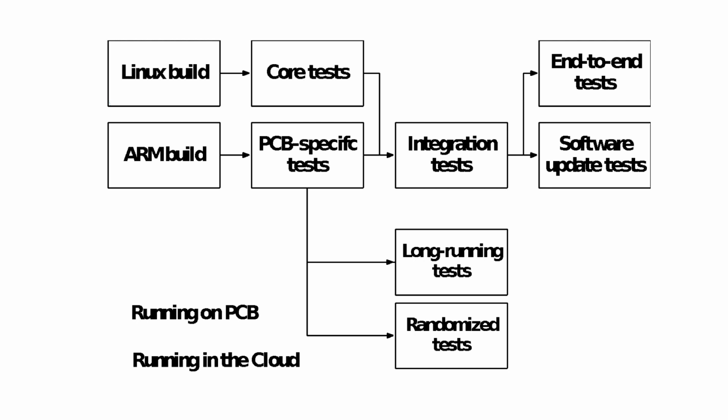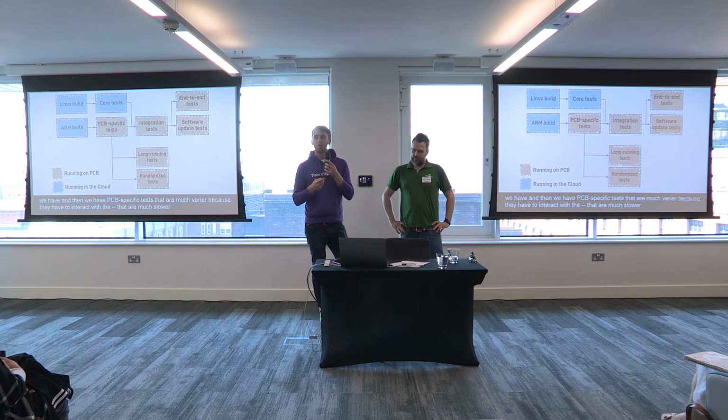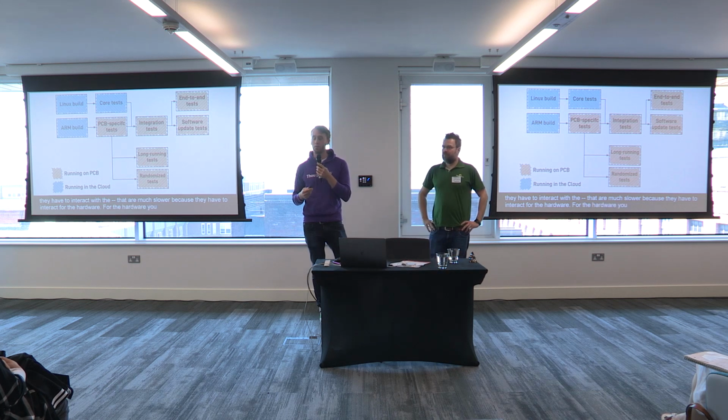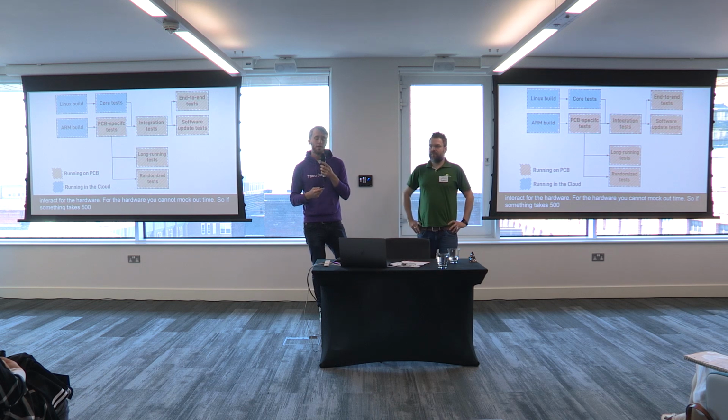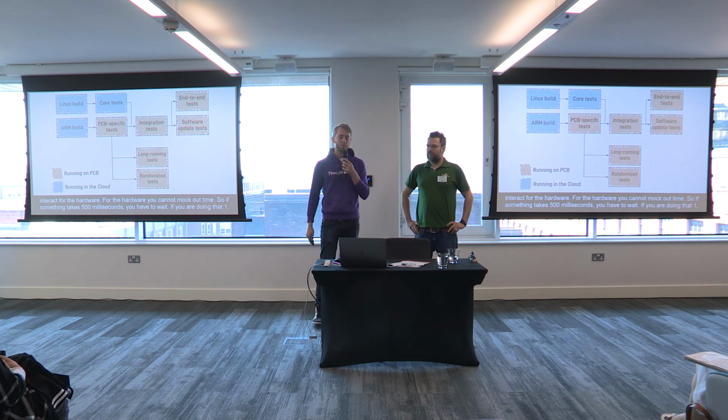But then we also have a lot of PCB-specific tests that are much slower because they actually have to interact with the hardware. And for hardware, you cannot do stuff like mock out time, for example. So if something takes 500 milliseconds, you actually have to wait for 500 milliseconds. If you're doing that 1,000 times, then yeah, that just adds up. So I think the entire run of our PCB-specific tests is currently at 1.5 hours.